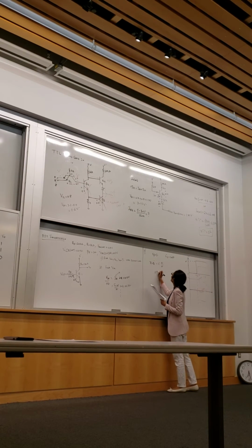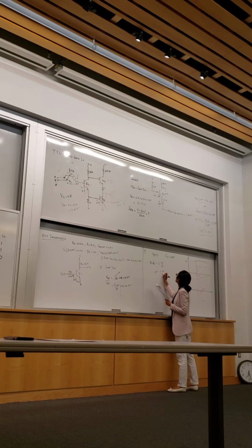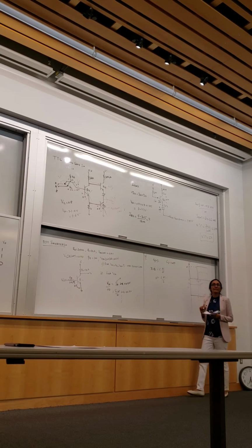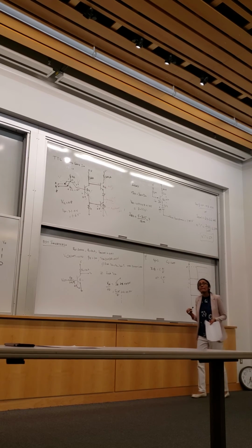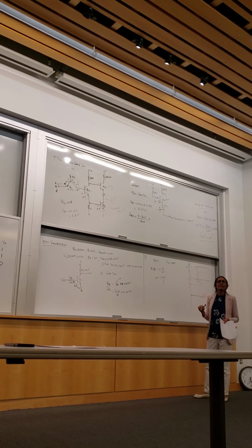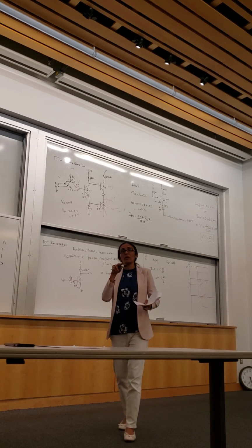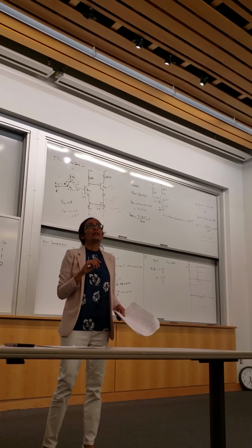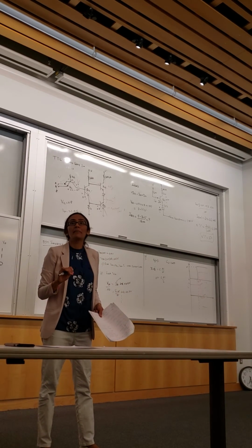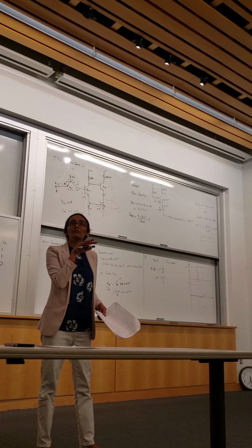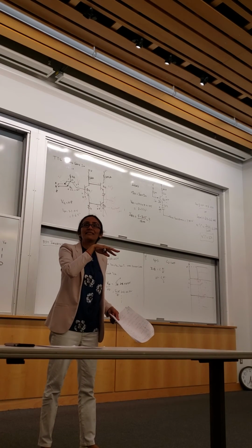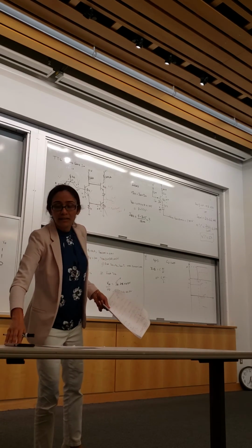So delta T would be C delta V over I. When we have that load capacitance, does it take over the role of the depletion capacitance or the diffusion capacitance? The way we did this analysis for fall time and rise time, for this particular interval, we mentioned that the load capacitance is much higher than the device capacitances. So we're not going to take into account the effect of the device capacitances. Yeah, so this one takes over.